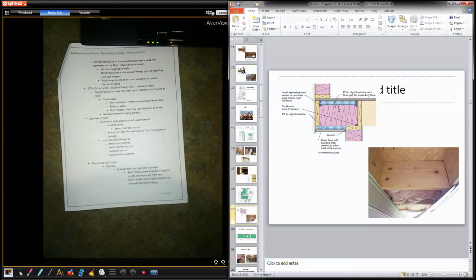So here's an example with styrofoam. So 1.5 inch styrofoam under the plywood, then bats, and then more foam. You see the ceiling where the red dots are. Spray foam here. So they're using this foam as the air sealing. So it's sealed to plywood, sealed to rim board.